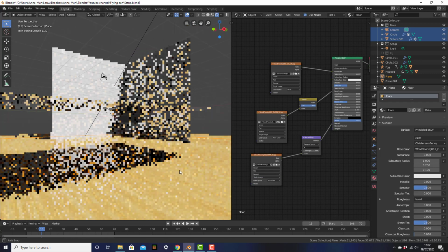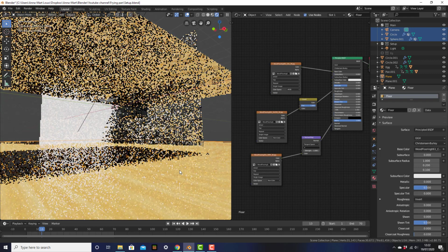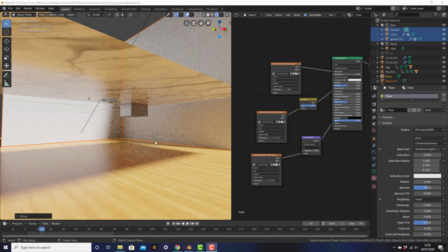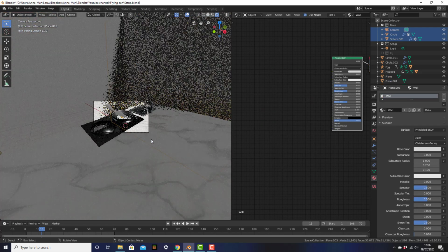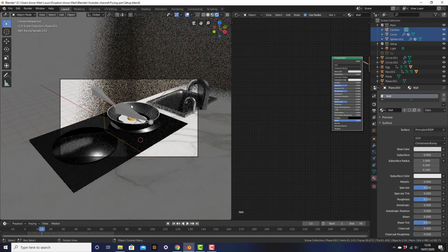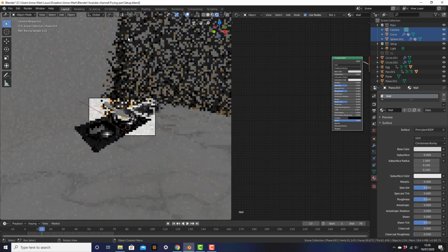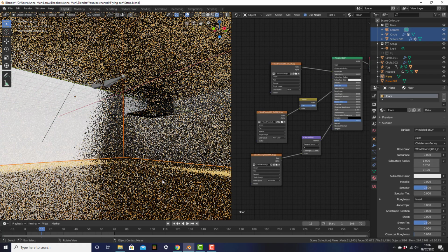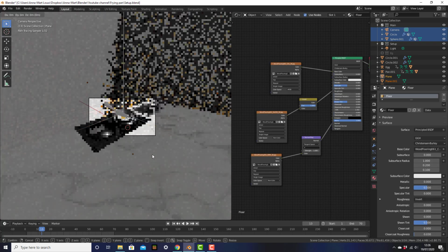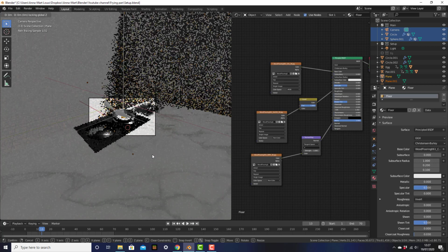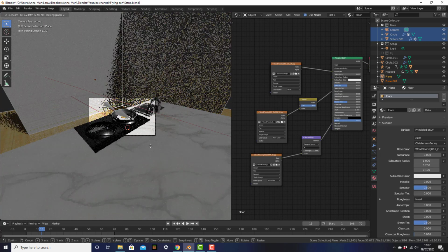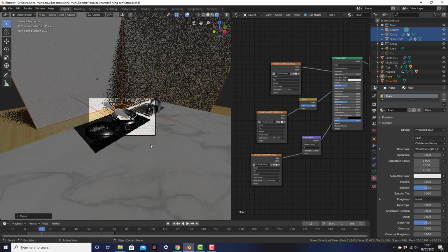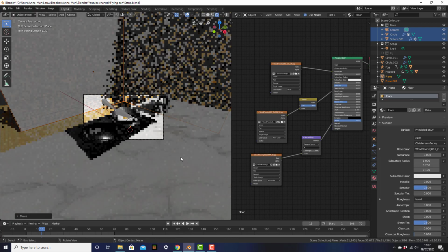And now if we move down here and zoom in a bit, you can see the texture of the floor looks really good. Now if you go to our camera viewport with number pad 0, you can see that the floor isn't visible at the moment. So we want to select the walls and the floor and move it back. So select the walls and then shift select the floor. And then press G and Shift Z to move it back on all of the axes except the Z axis. Till about there, so that the floor is visible. And then we can zoom back in.